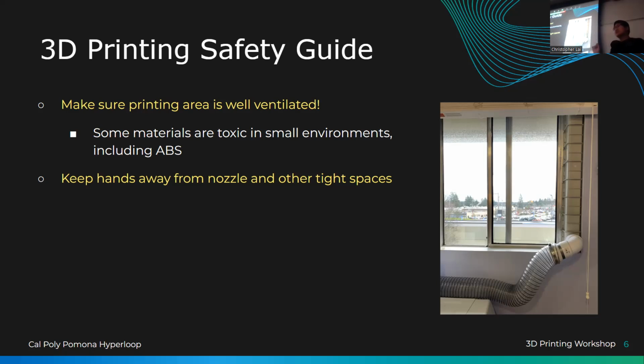When you're installing the nozzle, you're going to twist the nozzle onto the hot end when it's cold so that it's comfortably on there. And then you're going to preheat the printer to 200 degrees and then tighten it the rest of the way with a wrench or pliers. This way, the hot end is going to mesh with the metal on the nozzle and form a really tight, secure bond.